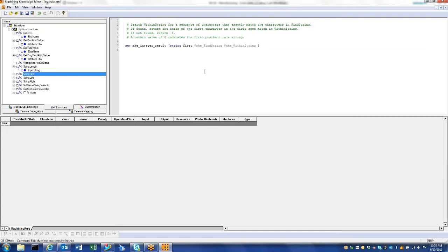This is a very strong, robust feature of NX, and you'll find that with any type of plate machining, within 5 minutes, even out of the box, you could probably have 90% of your program already laid out for you, and you just have to change tool diameters and adjust things to fit your tool crib. If not, having the author license lets you come in here and set your own features.